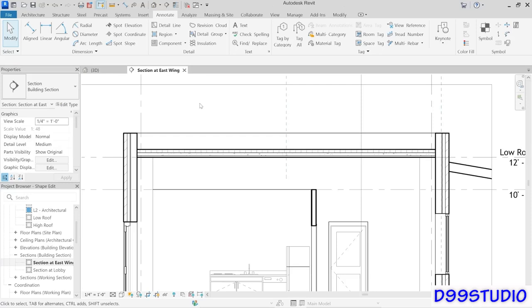Now, here in my Imperial file, this view is set to medium level of detail. If yours is not set to medium detail, please do that now. If it's set to coarse, you won't see any of the structure inside the roof. But if it's set to medium or fine, then you will. And you'll notice that it now has multiple layers of construction, just like our wall assemblies do. So roofs and wall assemblies use the same basic concept of being able to have layers of materials all sandwiched together. So that's the first step that I wanted to do.